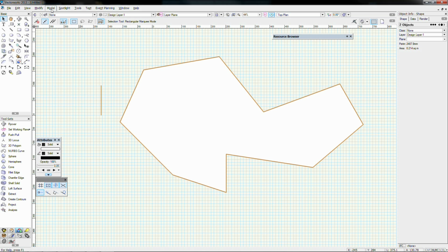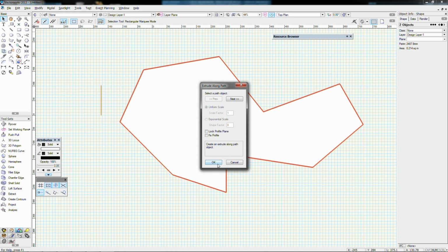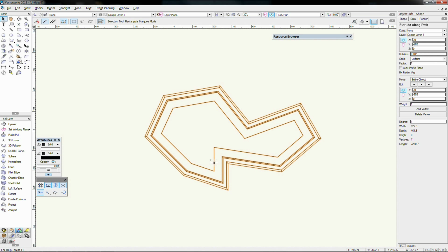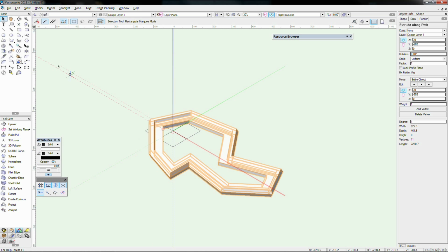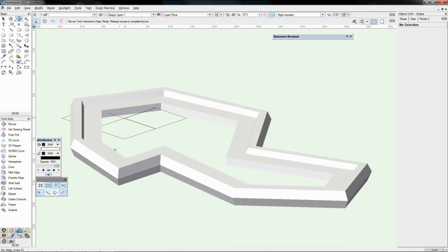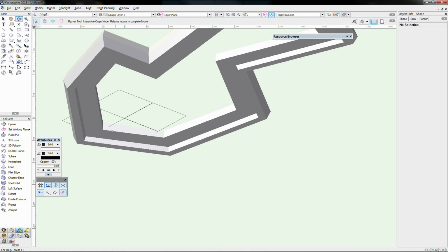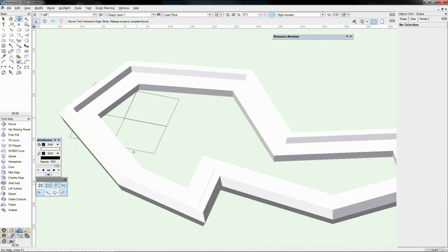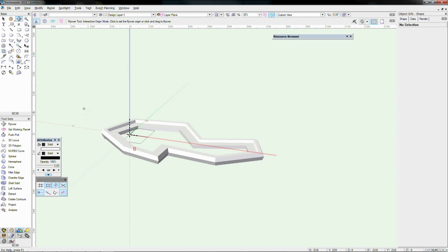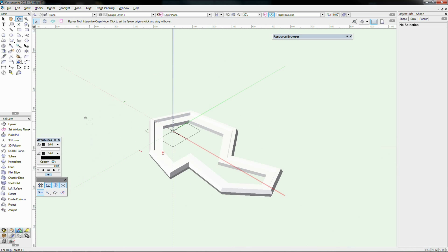Holding down shift, left clicking, model, extrude. Fix profile. Okay. Now, what we're going to notice here, and it's done a little bit differently to what I thought it would, is that it's actually kept that pointing to the interior this time. Everyone see how this has kept it always facing to the inner side, which is kind of handy. I didn't think it was going to do that. I thought it would keep pointing north, but I'm pretty sure that's the other checkbox that we can investigate now.